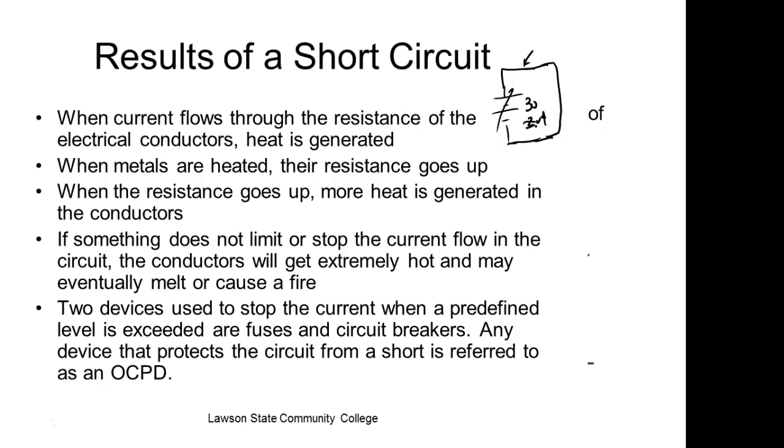But still, that's not going to replace you 100%. It'll help you on the wires that run through your wall, but it doesn't help you on those extension cords that we use all the time, right? So that means if you've got a 15 amp plug, then you need to use a 14 gauge extension cord, right? You understand that? So usually a short means the insulations came into contact with each other.